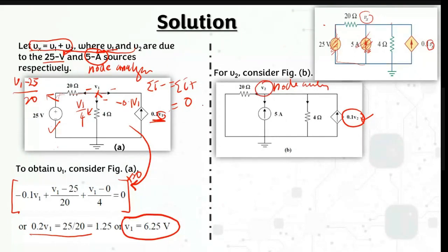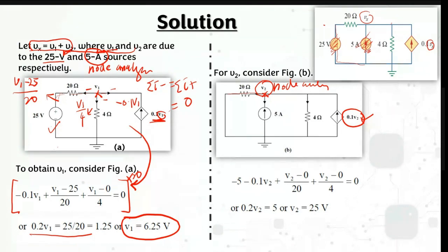Alright, so you can just draw the current directions. Seems like this previous one. Okay, so this is your node, and you have 1, 2, 3 current, which is leaving the node, and the other one is entering the node lah. Okay, so means that what you have here is you will have this one going to be negative, negative, negative, and then this is one going to be positive lah. Okay, so just put it as a positive current equal to the negative current lah.